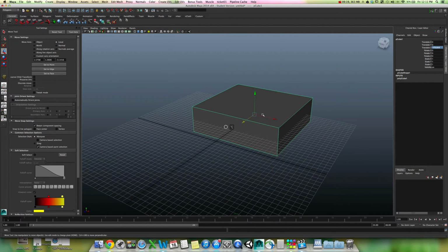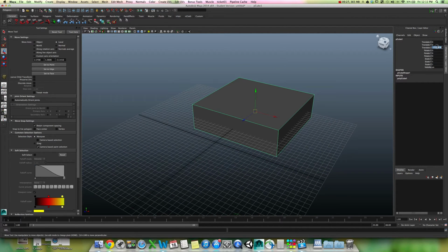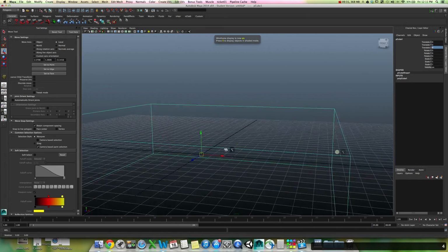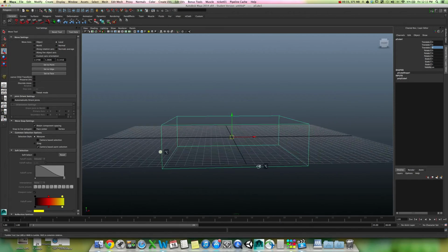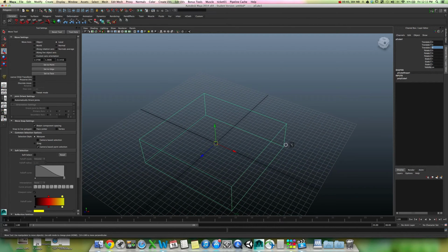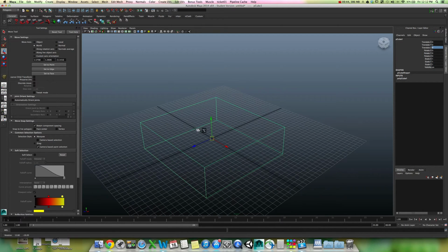So it is measuring where this point, which is our object pivot point, is from this point in space, which is the world origin. So of course, if I type in 0 here, I would expect, and I'm going to go to my wireframe mode here, for this point to be exactly in the world origin. And that's where it should be if all of these translates are at 0, and the object is not parented to anything. Okay, so world space, local space, essentially the same for this particular exercise, and both of them derive their coordinates from this origin point in the world.